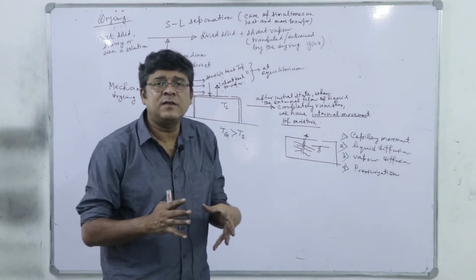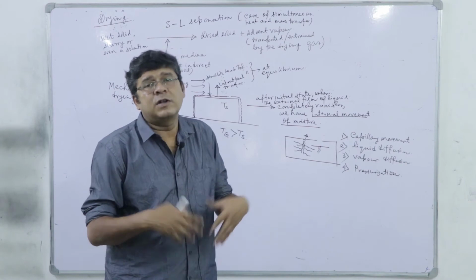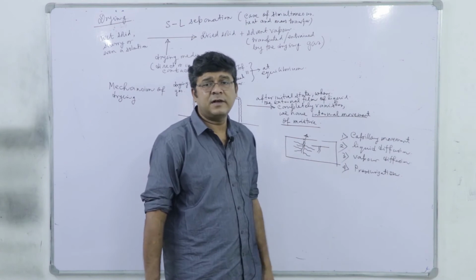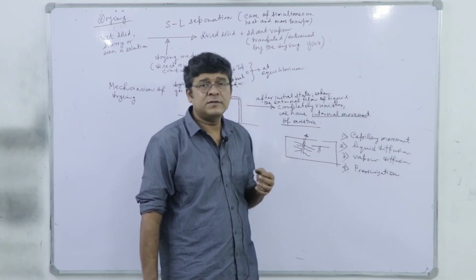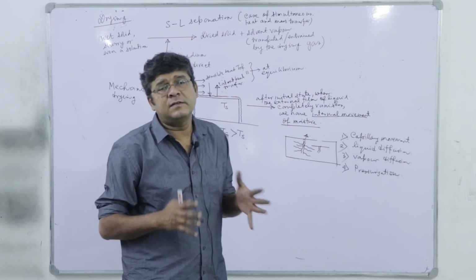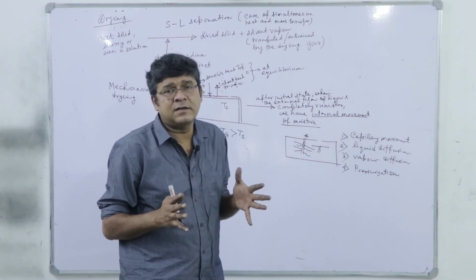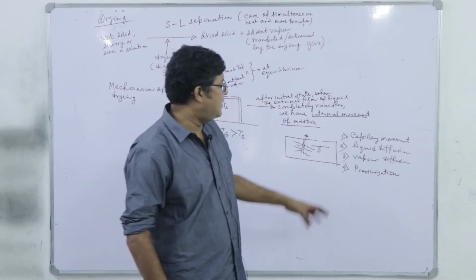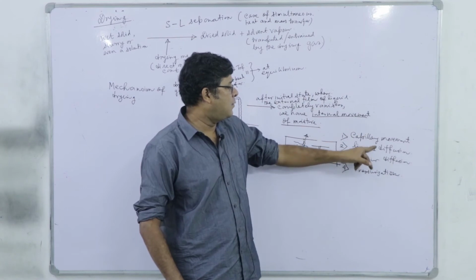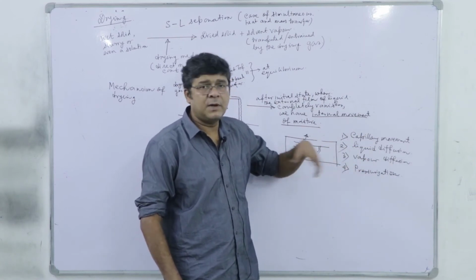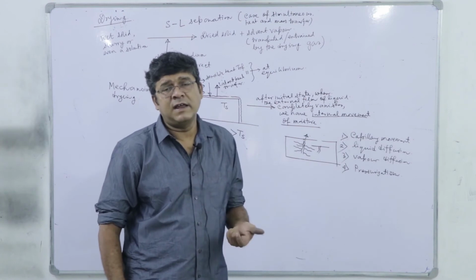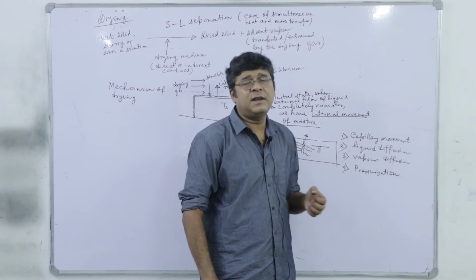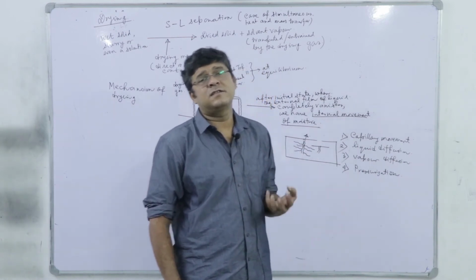Just like if I squeeze a wet cloth, what will happen? The water will spill out. So, the same mechanism is the transport based on pressurization, but that is not universal, because if the solid is not highly elastic, it is not going to deform because of drying. So then there will be no pressurization effect and we will have capillary movement, liquid diffusion, vapor diffusion, etc., as the governing transport mechanism for drying. Whereas pressurization is very probable where the solid shrinks upon drying.